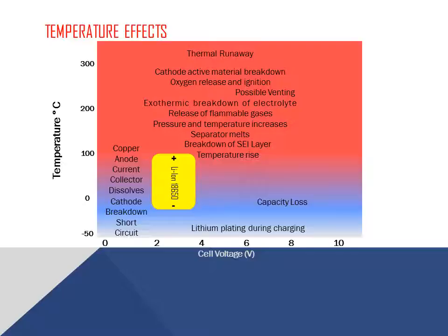As your intuition tells you, higher temperatures initially speed up battery reactions and reduce internal resistances. But after a period of time, as heat accumulates and temperature rises, the battery experiences thermal stresses and some components of the battery may start to decompose, leading to thermal runaway.